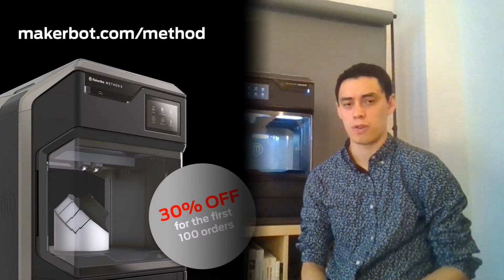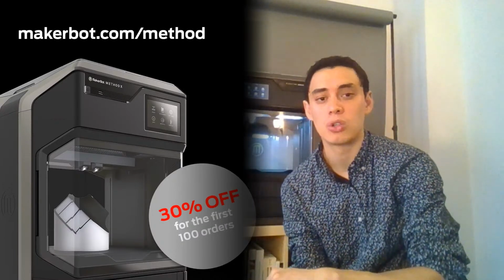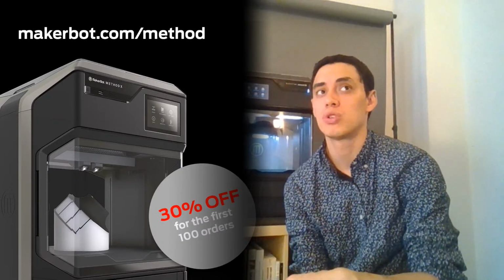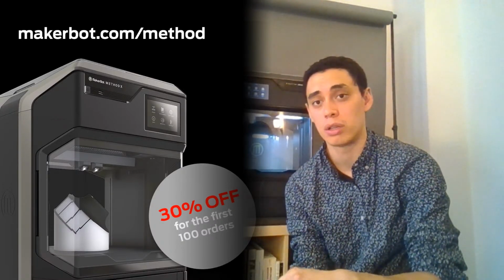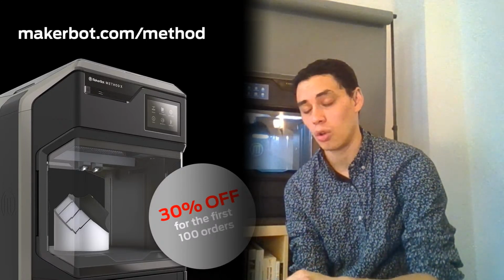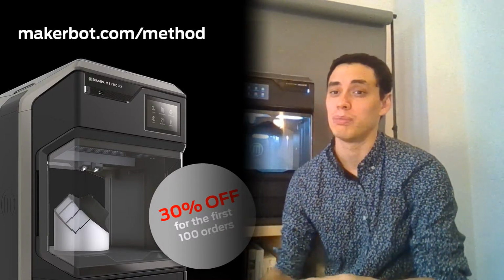I think it's over 30 of them. So yeah, how do you simplify a mesh? That's a good question. It depends on the type of mesh. One option is there's a command called mesh reduce in Rhino. There's also a few elements on Grasshopper that allow you to simplify the mesh.